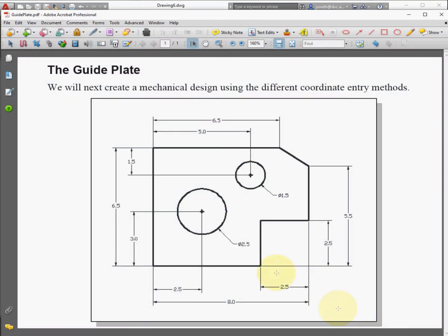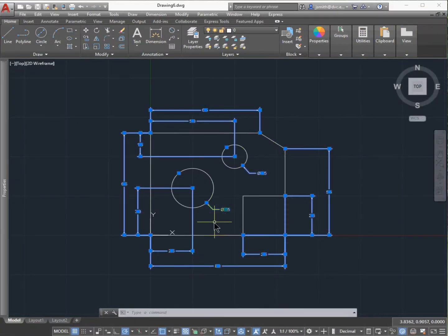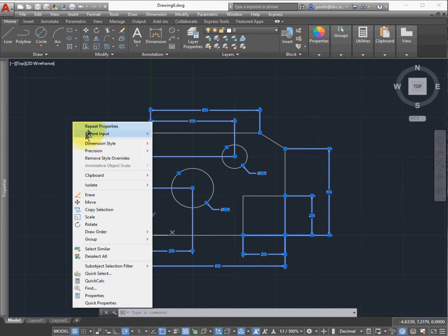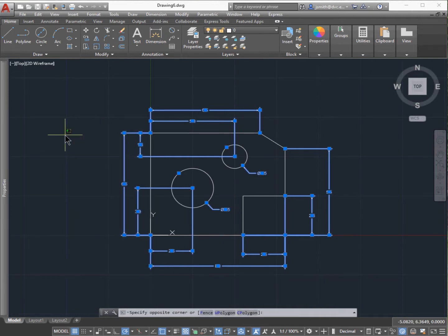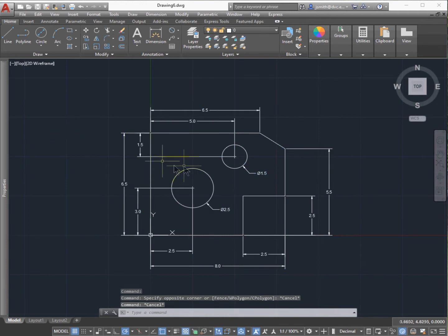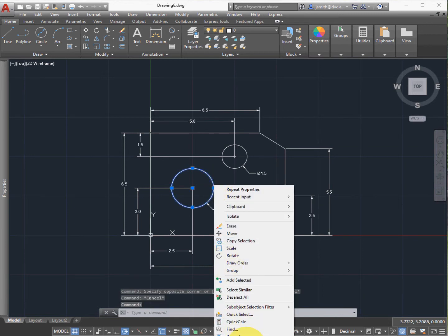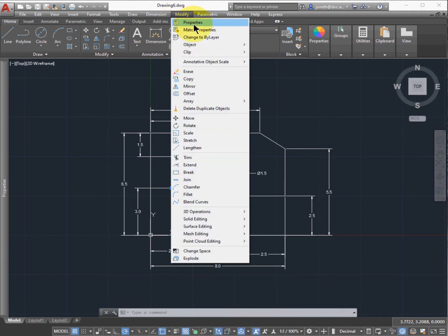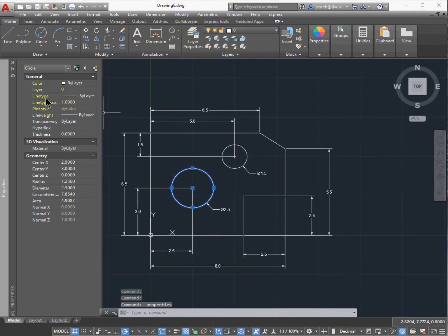And so the other thing you're going to notice is, boy, that part line is always going to be darker than the dimensions. So I'm going to go ahead and hit Escape. All right, and if I hit Escape, that'll kill all this right now, so you want to do that. And then what I want to do is select the line. So for example, let's go ahead and select any line, and I'll show you the same exact thing. Right click on it and hit Properties, or go up to the Modify on the tab and hit Properties, and you're going to see something that says line weight.